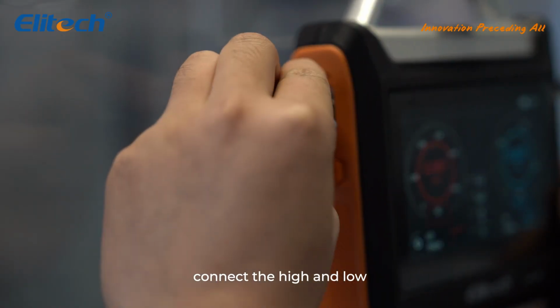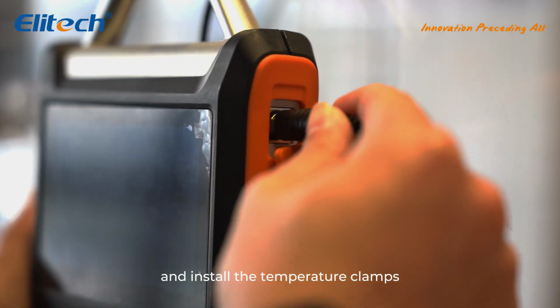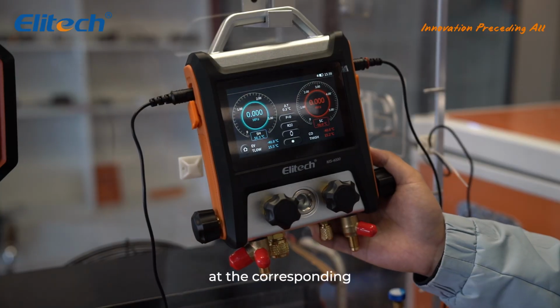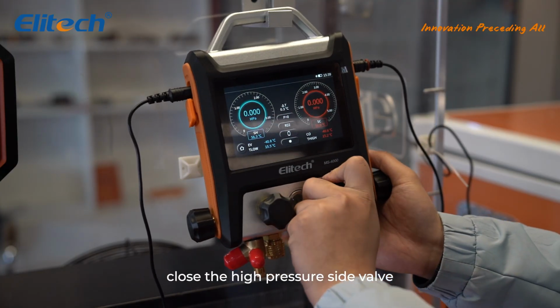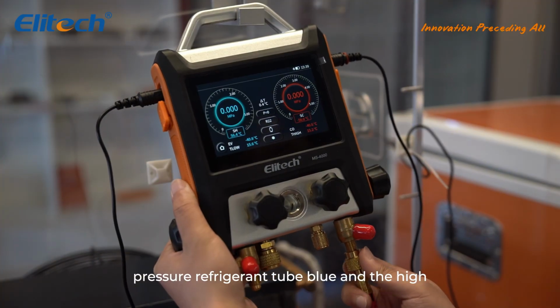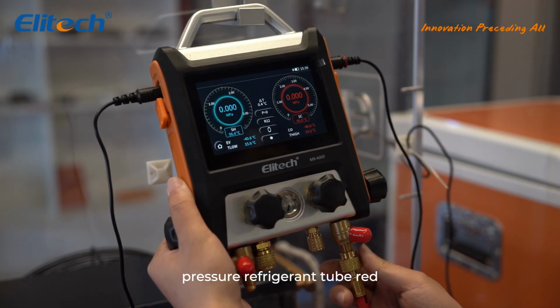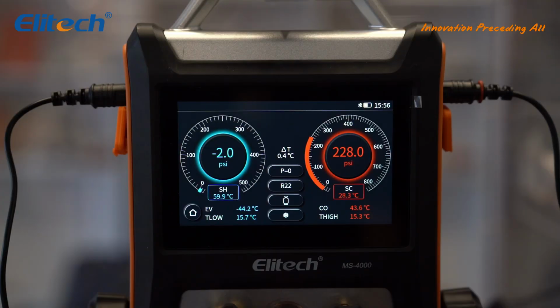Connect the high and low pressure temperature clamps on both sides of the main unit and install the temperature clamps at the corresponding measurement positions of the system. Close the high pressure side valve. Connect the low pressure refrigerant tube, blue, and the high pressure refrigerant tube, red, to the instrument respectively and connect them to the measured system.